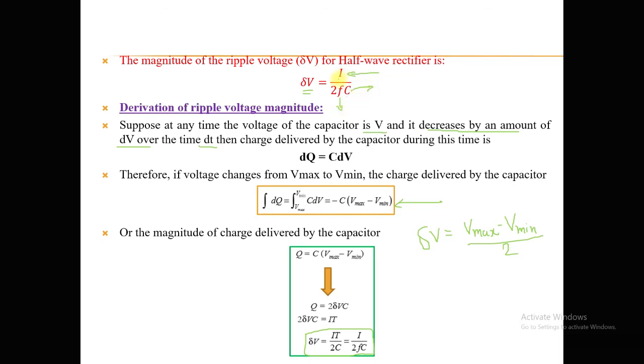So this load current value depends upon the load. We are actually connecting a fixed load. So it is not a feasible solution to control this delta V by controlling the load current value. Okay, because if you are changing the load current value, ultimately you are changing the input voltage, but we need to test our insulation at a fixed voltage value. So the control of delta V by controlling the load current is not a feasible solution.